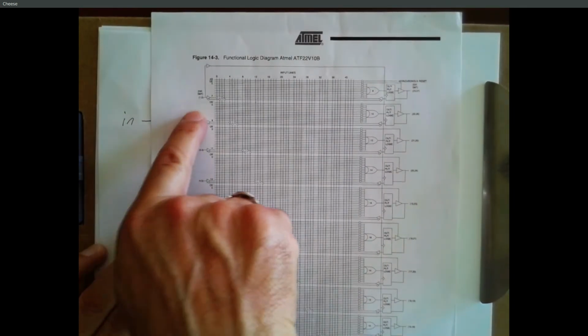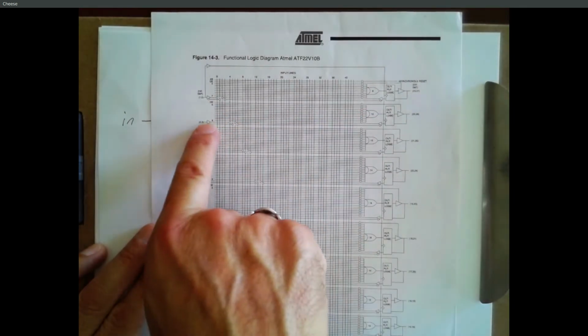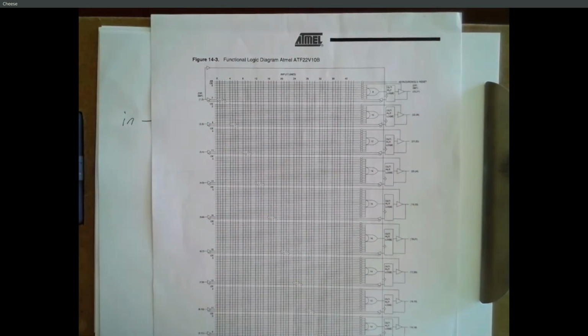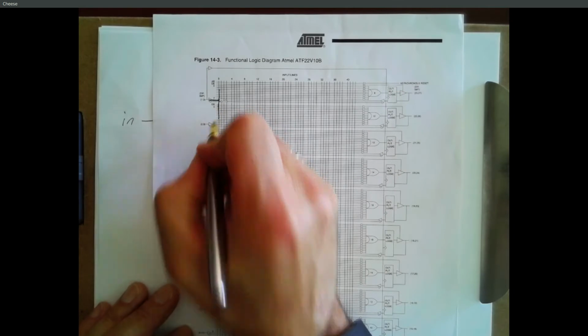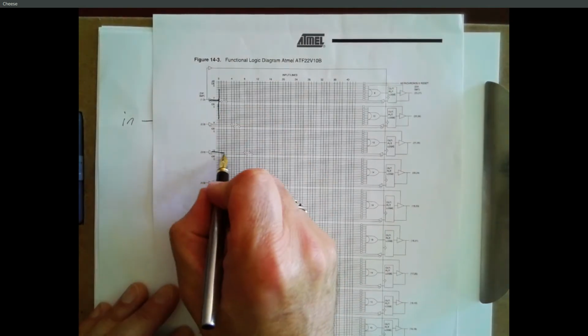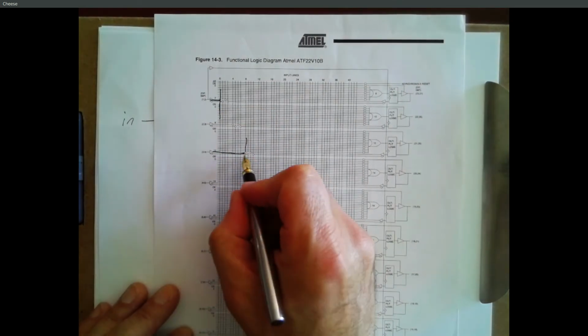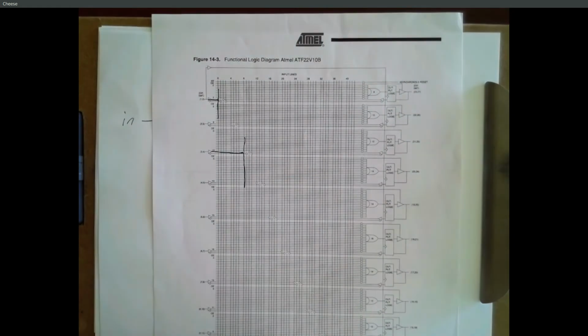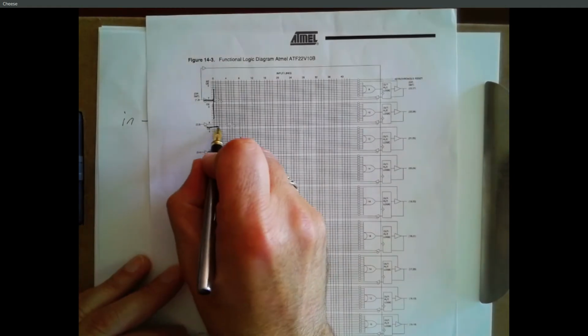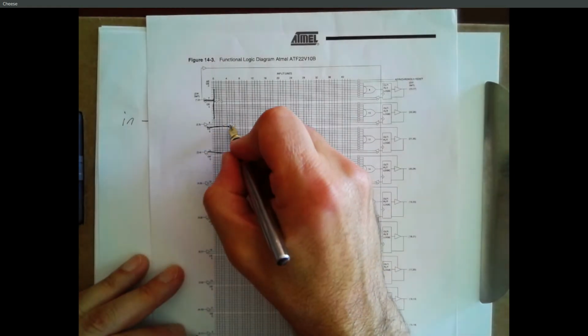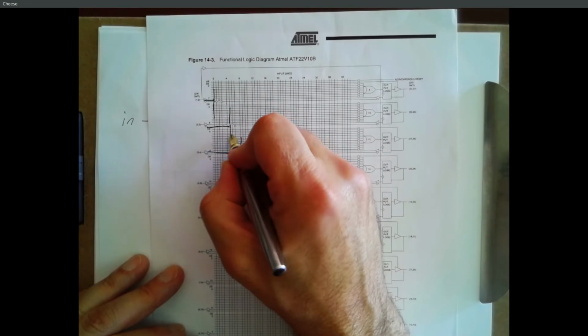You have inputs that we could usually have going in from the left, but we farm those off. So this input here actually runs vertically along this line. This third input comes across here and runs vertically on this line. Right, so we have these long vertical lines that carry our inputs, or the inverse of our inputs. So here's an inverse of that second input, and it runs on this vertical line.